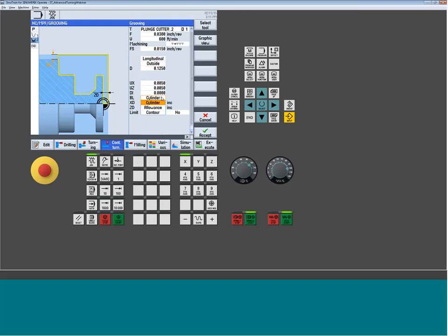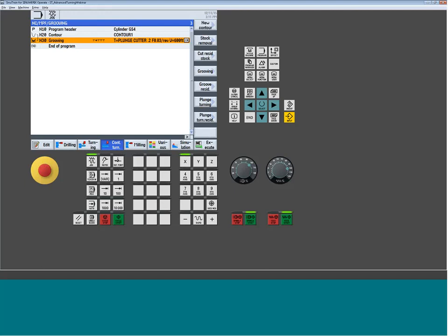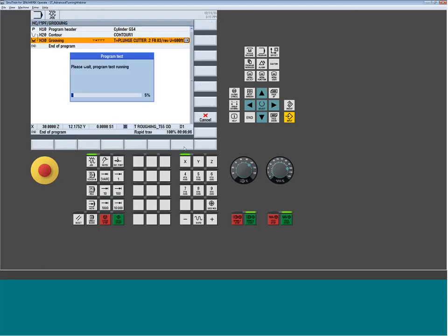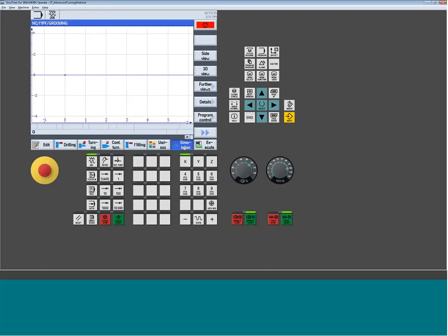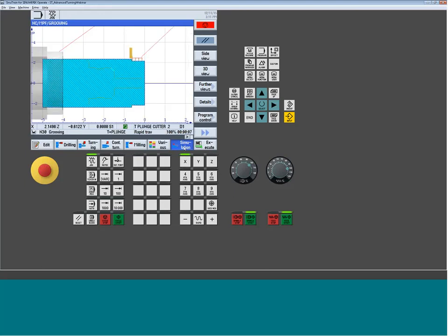All of the things I just showed you with the contours and the allowance for the stock could all be leveraged in these cycles the same way. But I fill out the page, I hit accept, the two are linked together, and now we're going to see a grooving cycle. So in a part like this, this certainly would not be the most proficient method for machining the part, but depending on the geometry, it could be. If I knew that there was a straight feature up here and back and this was a groove, well, there might be too much area that I'd have to flip between right-handed and left-handed tools, that the little bit of cycle time loss I have here would potentially still be quicker. So that's where you got to kind of play with how you leverage it.